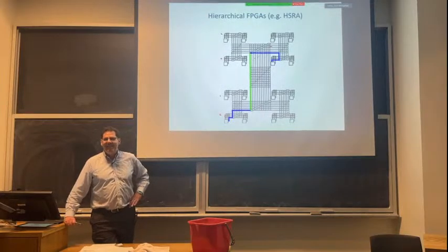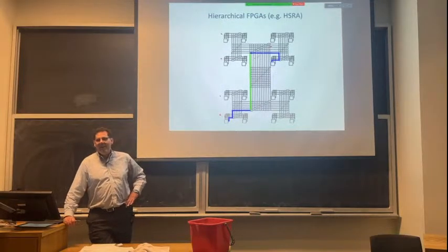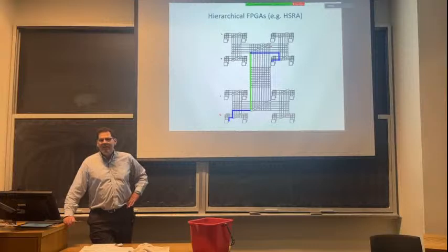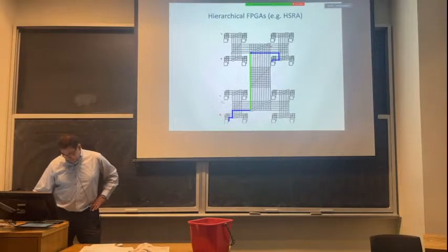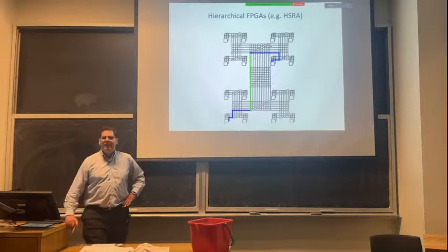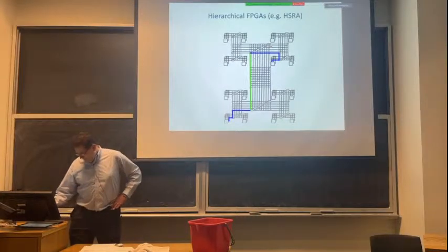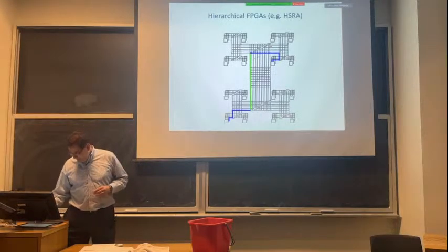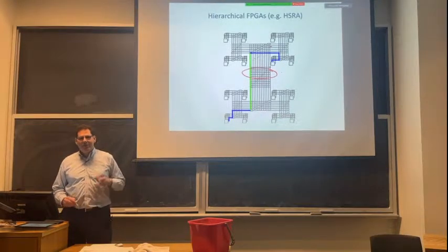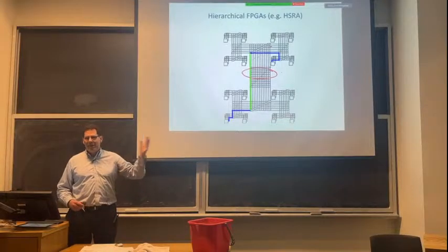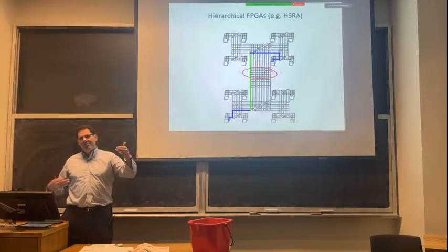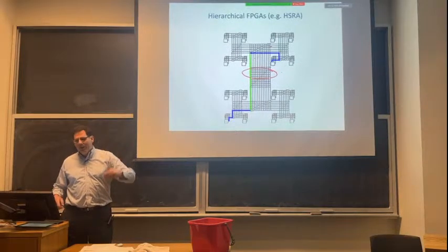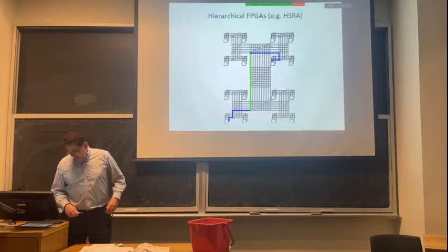I think L1 wires are supposed to be longer. Yeah, there should be more of them, for sure. Yeah, because they are at the lower hierarchy level. Yeah. And they cost less. Yeah, they cost less. These wires look big, right? So visually they look big. They are visually big because they are big. These wires at the upper level of the hierarchy are connecting relatively distant parts of the chip. So is that a problem?